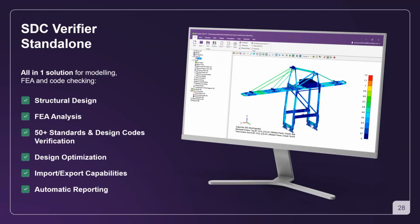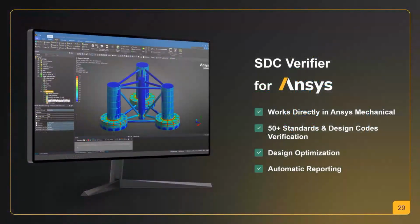But then we also have some other software. This is SDC Verifier for ANSYS. It is basically an extension to ANSYS: you calculate your models and perform your analysis in ANSYS Mechanical, and then simply connect SDC to it, and SDC is going to read all the results from the performed analysis and perform the checks.